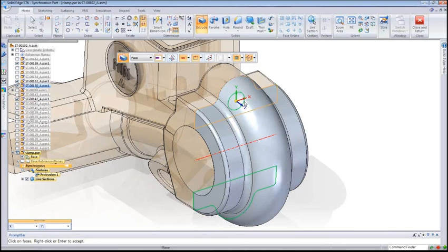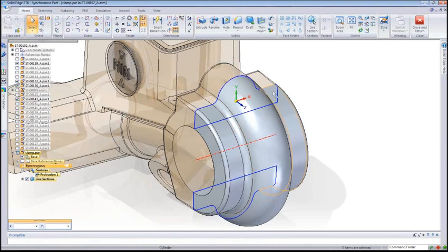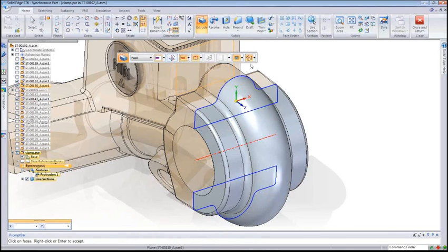Oh, I want to make sure this is a remove. Right-hand click, and you'll notice what's happening here is that I actually am pulling in a hole. Now, I could do this by edge also, which it looks like I missed my bottom one, so I might have to come back there and add that again. Let's see if I can grab it one more time. Extrude, remove, and I did choose use only internal loops. I'm going to get this one, and I'm going to get this one. Right-hand click. Yeah, oh, okay.